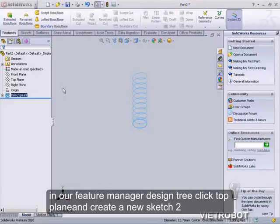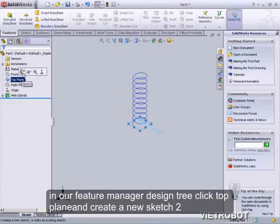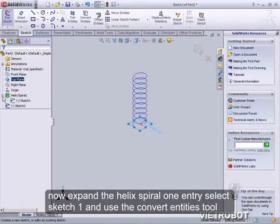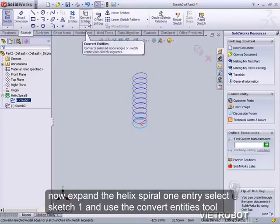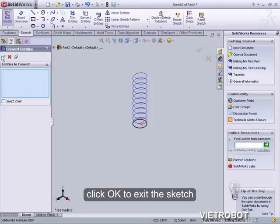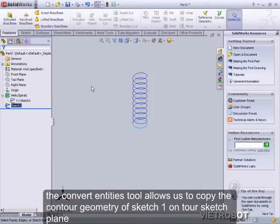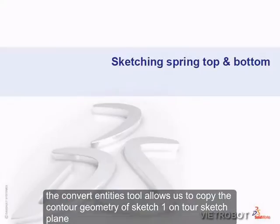In our Feature Manager design tree, click Top Plane and create a new sketch on it. Then we'll expand the Helix Spiral 1 subtree. Select Sketch 1 and use the Convert Entities tool. Click OK to exit the sketch. The Convert Entities tool allows us to copy the contour geometry of Sketch 1 onto our sketch plane.